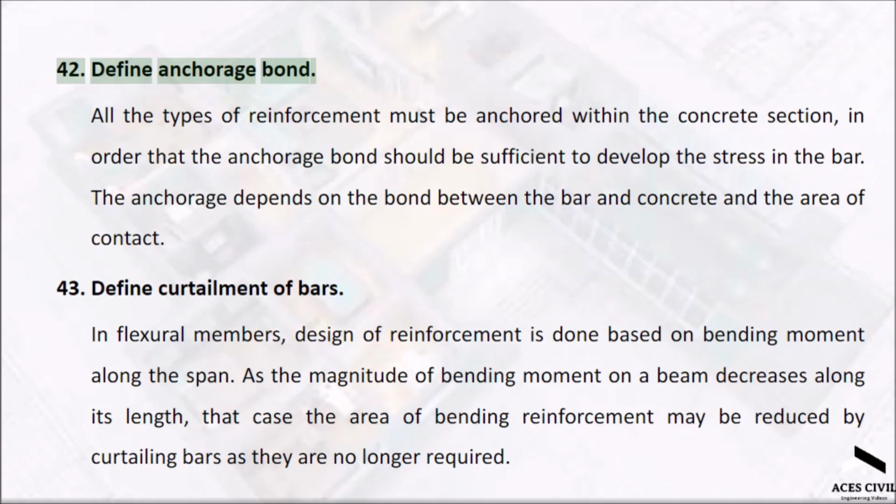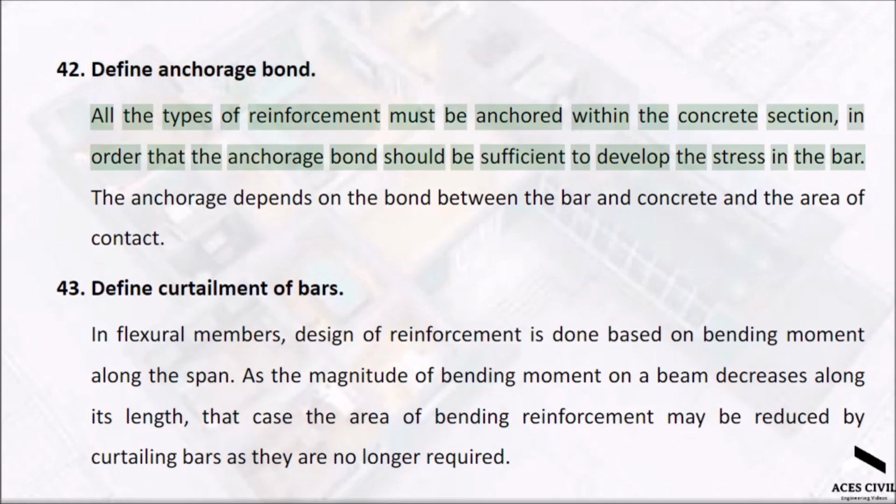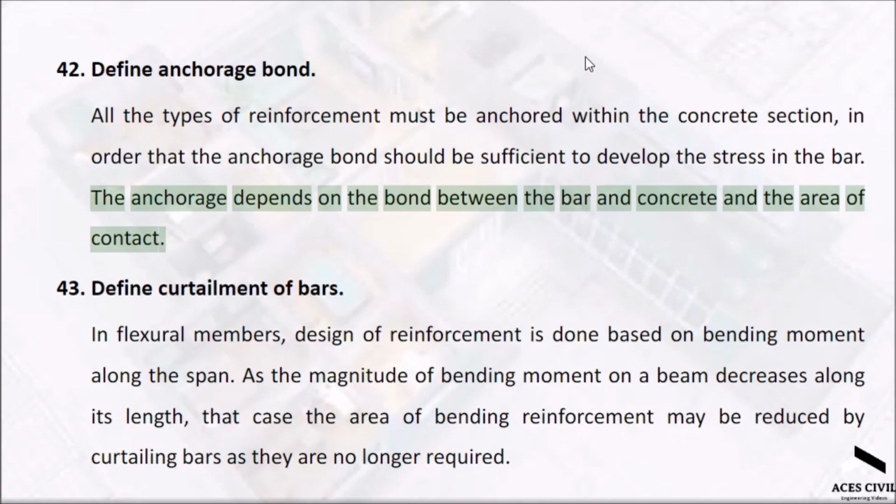Define anchorage bond. All types of reinforcement must be anchored within the concrete section, in order that the anchorage bond should be sufficient to develop the stress in the bar. The anchorage depends on the bond between the bar and concrete and the area of contact.